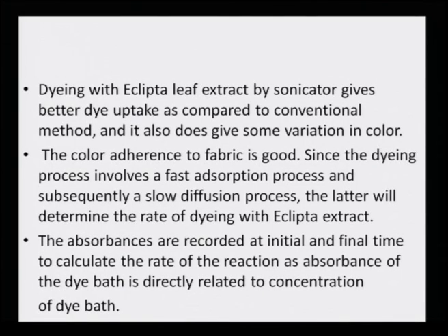Dyeing with Eclipta leaf extract by Sonicator gives better dye uptake as compared to the conventional method, and it also gives some variation in color. The color adherence to fabric is good. Since the dyeing process involves a fast adsorption process and a subsequent slow diffusion process, the latter will determine the rate of dyeing with Eclipta extract.